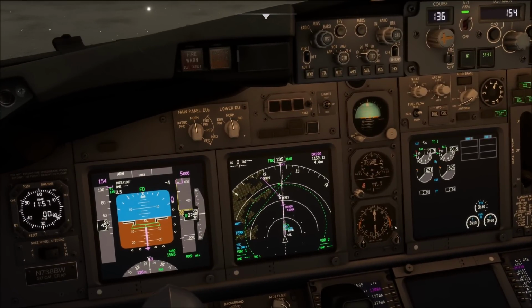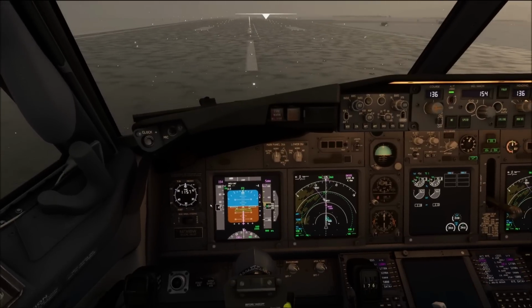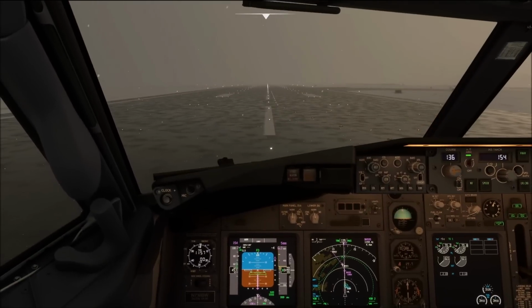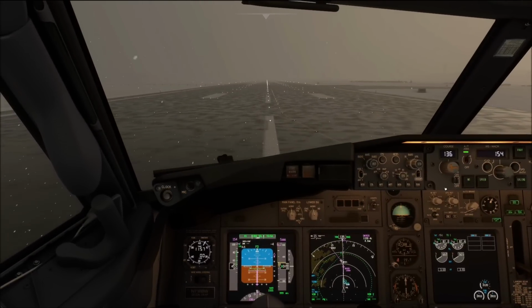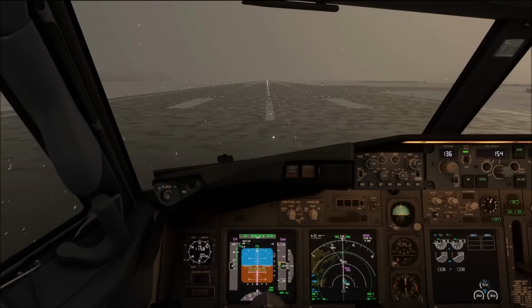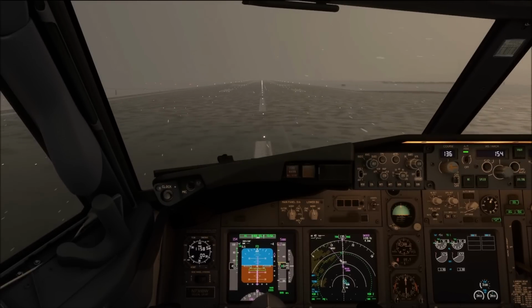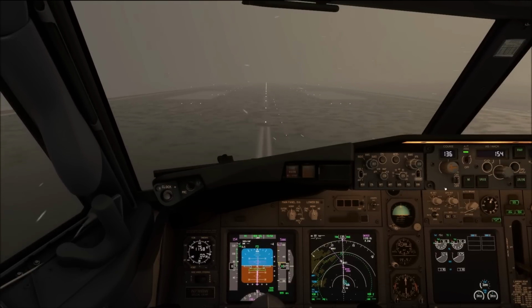It may be a good idea to inform the passengers over a PA prior to carrying this out, as it will feel quite uncomfortable to them. Okay, we've completed that 30 seconds. The secondary engine display has not come up. Let's start the timing, and from here, 70% stabilized, set takeoff thrust. Takeoff thrust set, indications normal. 80 knots.